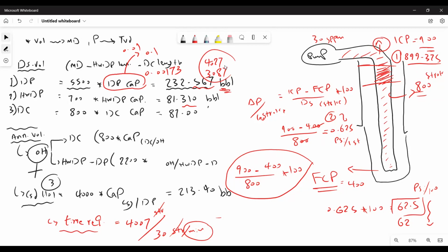it's easier to handle the whole calculation, as we're going to use this factor for the weight and weight method. For the weight and weight method, we need to make a step down table like this. Here is number of strokes, and here is drill pipe pressure. So we need to keep the drill pipe pressure as an integer number, not a decimal number. So once rounded down, we add overbalance. Let's say the calculated value for the pumping is 62.5. So 62.5 is the actual value. If we round it down, it will be 62.